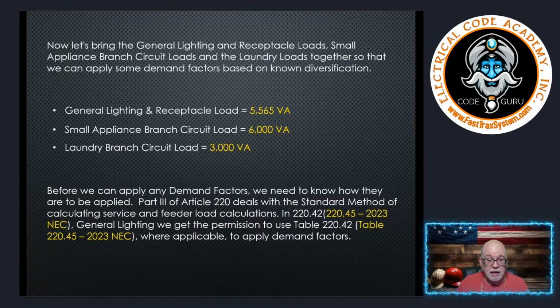Now, again, if it's a multifamily building that has a laundry facility on site, then you have some allowances to be able to not put the laundry receptacle in because it's available to all the tenants or all the people at the complex, and there's a separate laundry facility. Then that's different. Then you don't have to install the receptacle at all, but you're required to have the laundry circuit. And in a single family dwelling, you're required to install the laundry receptacle outlet. Okay? And I believe that is in 220.52(D), if I'm not mistaken.